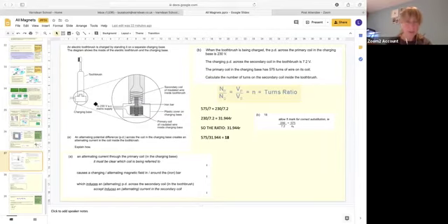So I've got my charging base here, which is connected to my alternating current 230 volts mains supply. Here I've got my iron bar coming through at this part here, and that then is going to set up, in the base of my toothbrush, a secondary coil of insulated wire inside the toothbrush itself.